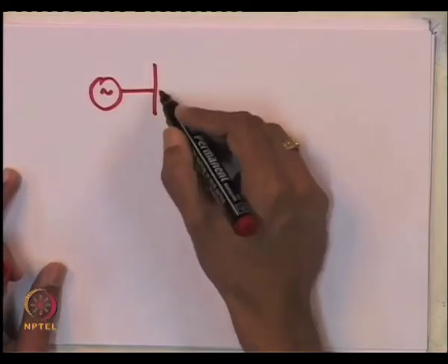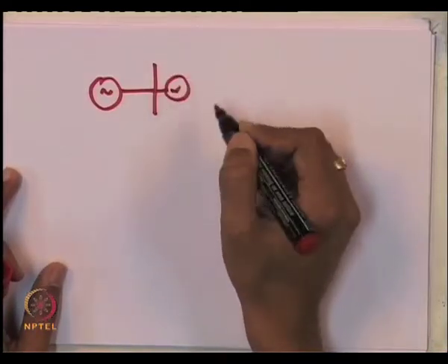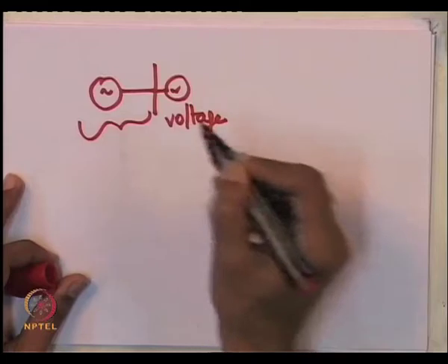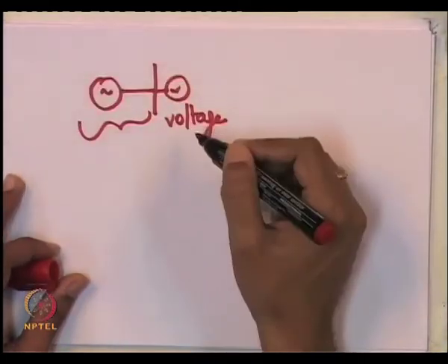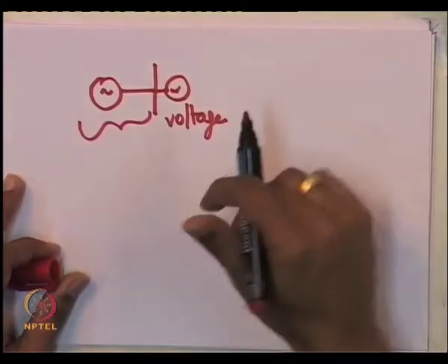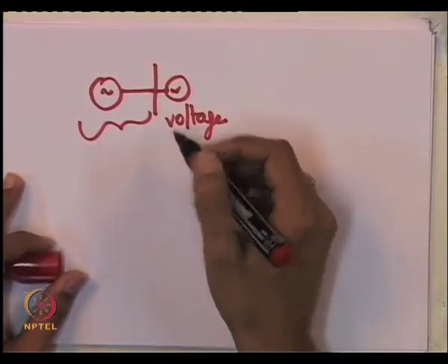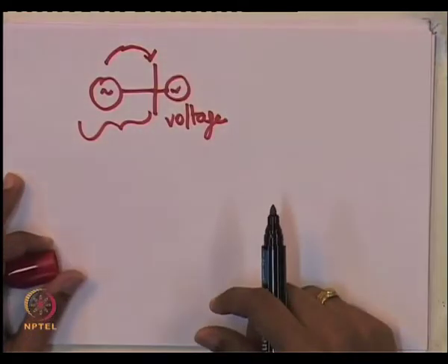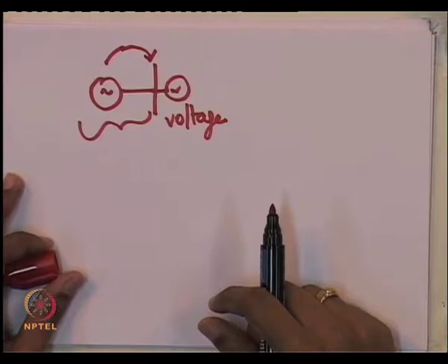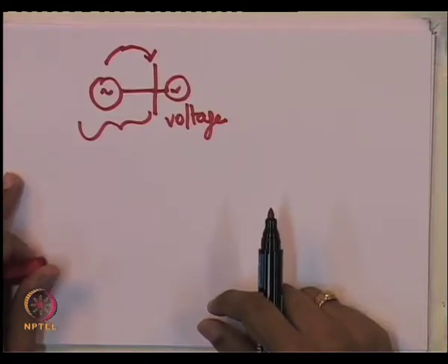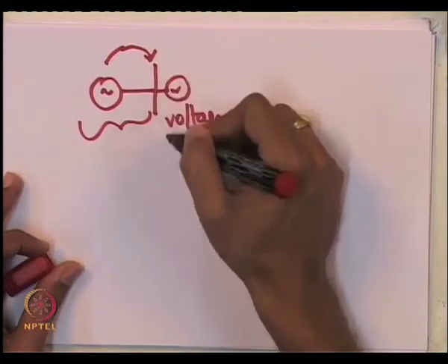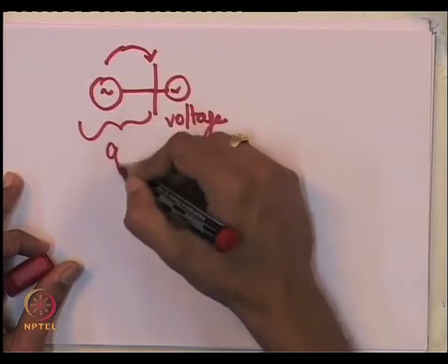in case you have got a generator directly connected to a voltage source in this fashion. Of course, this is a symbolic representation of the generator. The generator itself is not a voltage source, it is represented by the equations which I have already shown you. Now, the aim of the AVR is trying to maintain the voltage of this constant. Okay. So, constant or near constant. In fact, if you are using a proportional gain, it is near constant, not perfectly constant. Okay. Now, as I said, this does not make any sense if you have got a perfect voltage source here to which this generator is connected.